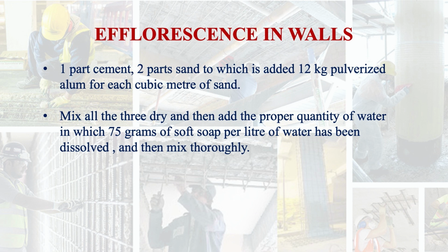Mix all the 3 dry and then add the proper quantity of water, and in this water that we have added, add 75 grams of soft soap per liter of water and then mix it thoroughly. So, you will get a waterproof mortar. It will also prevent the efflorescence.